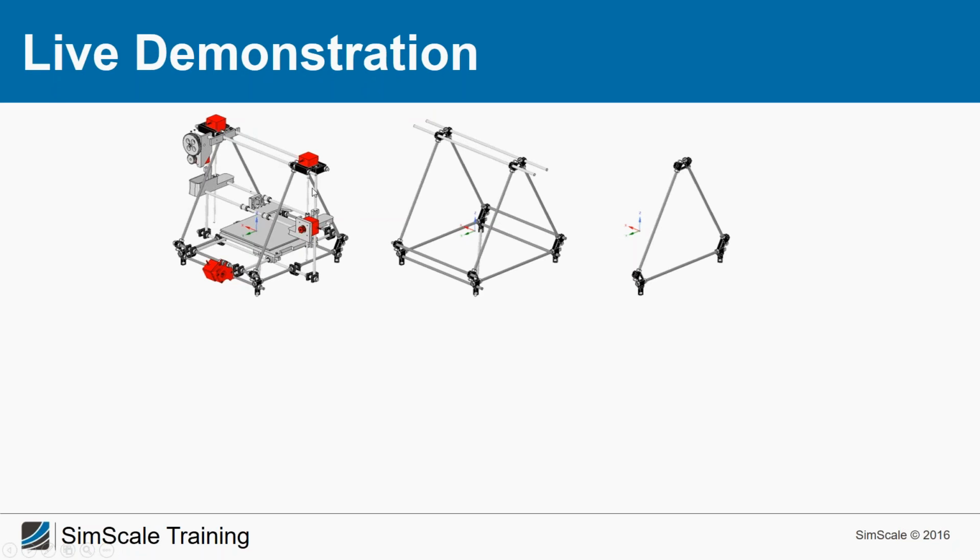And basically a very big problem in manufacturing, not only for 3D printing but also for milling, is that vibrations can result in worse product quality. Because just imagine, if this frame starts to vibrate, everything is moving, so also the head of the printer, the extruder, and when the extruder is also vibrating, this will make it very difficult for you to control the position and therefore to ensure the right setup of the different layers when your part is printed.